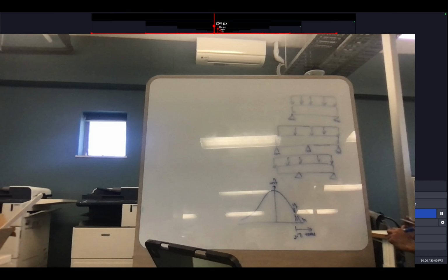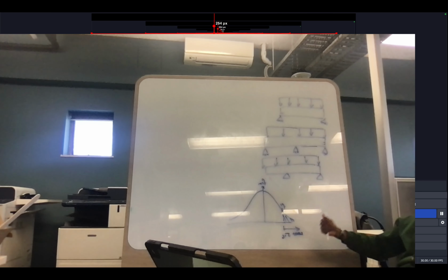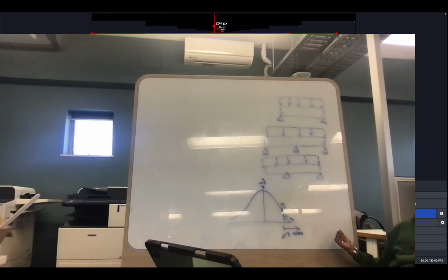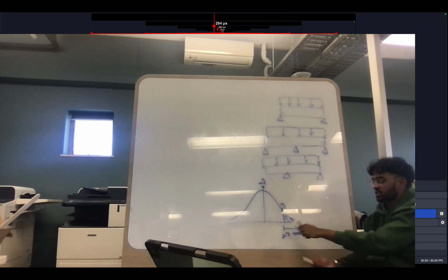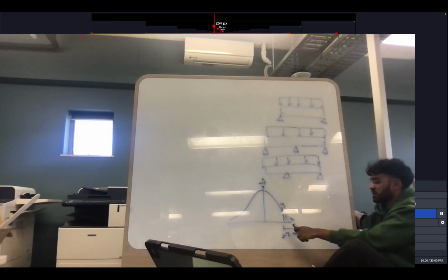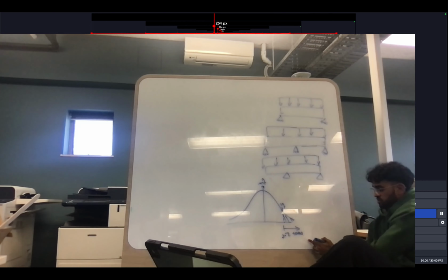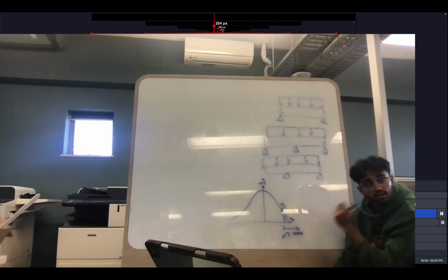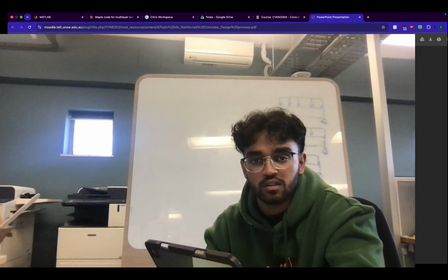Right, so, as you guys know, when we're designing, we design for the worst case scenario. That's why we take the last 5%. This is actually how they calculate F dash C, not through apparatus and so forth. They take the FCM, do a bunch of tests to figure out Z values, and then calculate this statistically. So what is F dash C? It is your characteristic compressive strength.